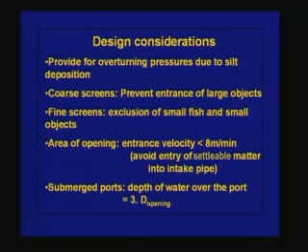So to prevent that vortex formation and the air entry into the inlet pipe, if there is a submerged port, then the depth of water above the port should be a minimum of 3 times the diameter of opening. This is very important, because air entry into the intake pipe and subsequent transmission of this entrained air through the suction pipe to the pump can cause damage to the pump in no time. So we should avoid this.